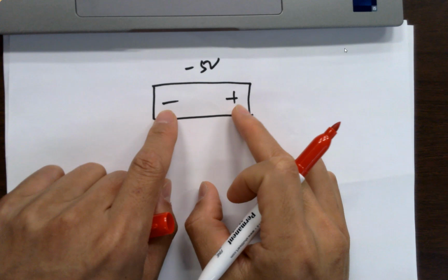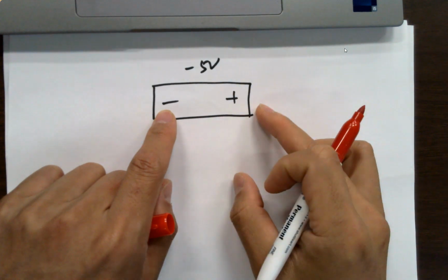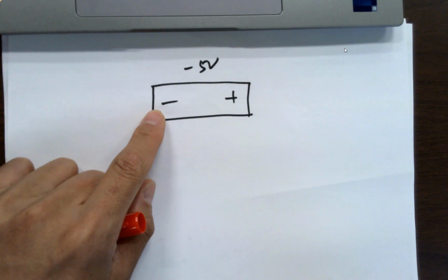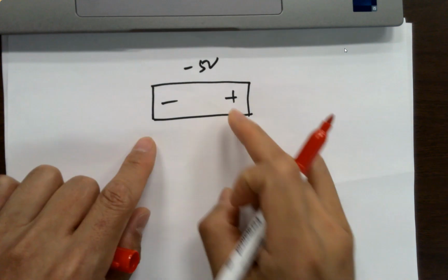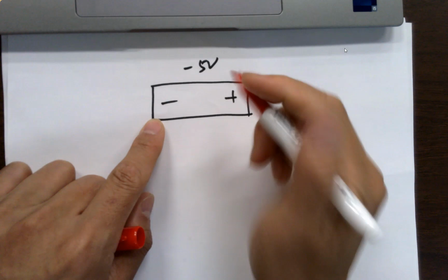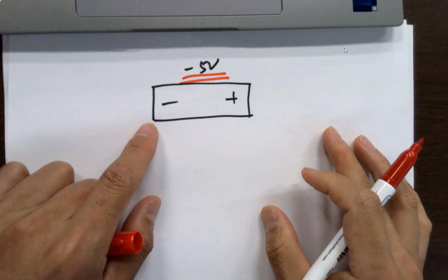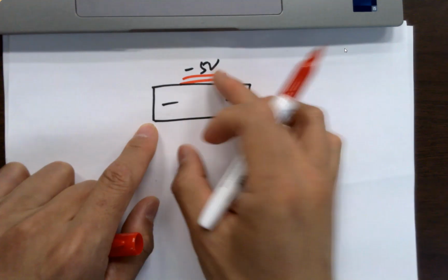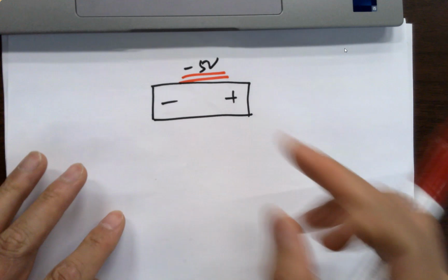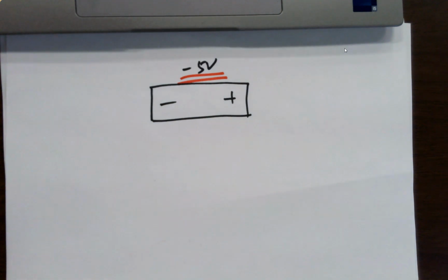So plus minus is labeled that way, but it doesn't mean that physically in the circuit you are getting a positive voltage drop from here to here, because it could be labeled as minus 5 volts. It's just on the paper, in the textbook, in the problem. It's just labeled that way. So how to deal with it? Voltages can be labeled with different polarities, and currents can be plus, minus, different polarities.